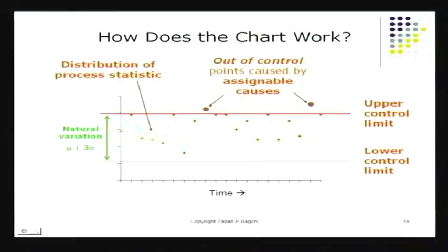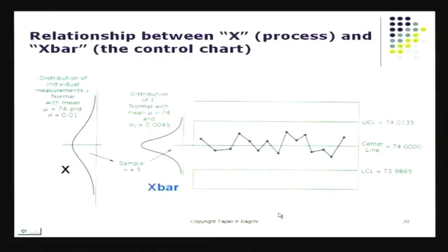When there's production going on to produce hundreds and thousands of these parts, you don't want these parts to be produced such that they actually violate the specification limits or they are unfit for the user's use. These are not going to be good news for anyone. So we plot the chart and we try to see, are there any points that have gone beyond the control limits? If they have, we have to stop the process and do some investigation.